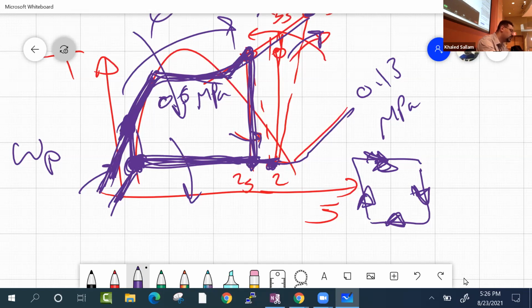This part is okay, this is not okay, but they try to make the turbine as isentropic as they can. But in real life, it's not. And that's why in real life, the Rankine cycle is not the Carnot cycle, because the turbine is not isentropic, and the heat addition is not at constant temperature.